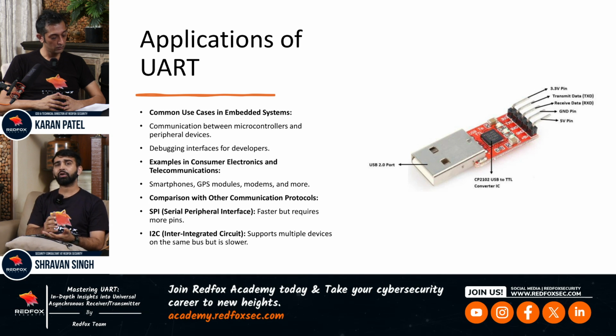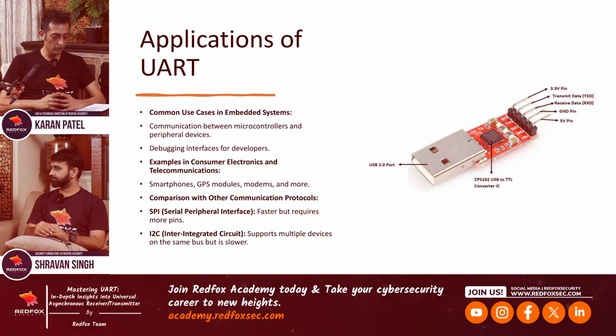In UART, if you are connecting, then during the boot process we can dump the firmware and analyze the firmware serially. That's why UART is a very common and user-friendly protocol. JTAG also has multiple pins, which makes it more complex. SWD and other protocols are also there, but they are more complex and not user friendly. UART is more user friendly and easy to use, and it consists of 4 pins: VCC, GND, RX, and TX. That's it.